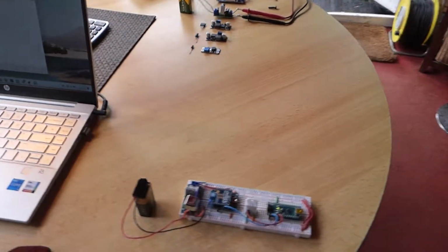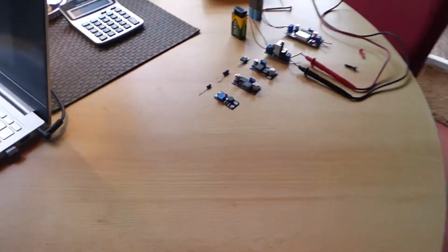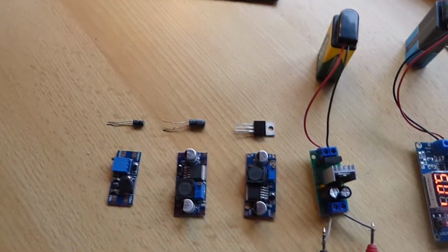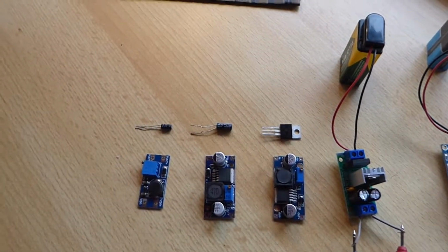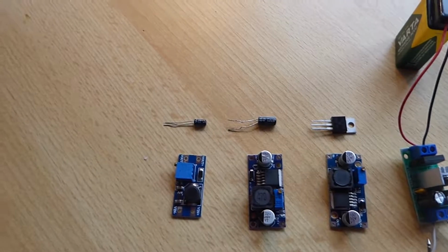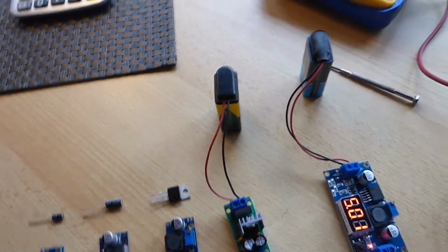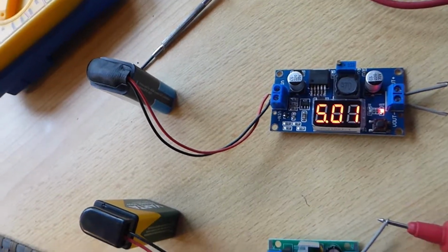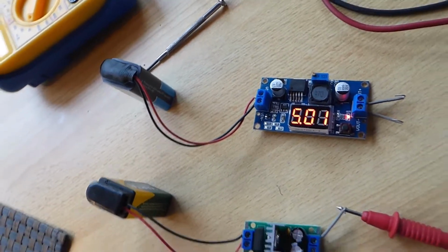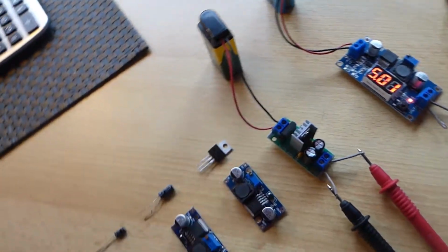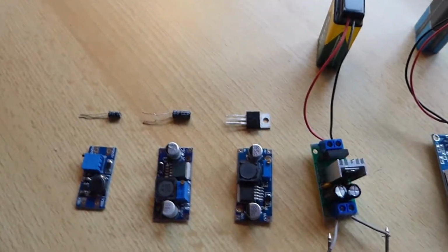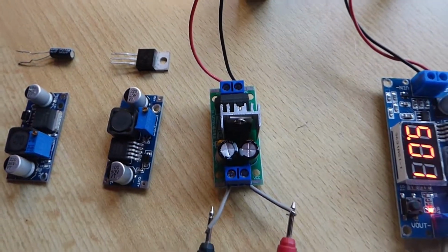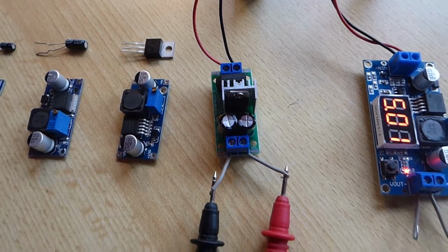Two years ago, when I described the miniaturized system, I pointed out that there were alternatives to using the 7805 5-volt regulator and two electrolytic capacitors, in order to take a 9-volt battery and reduce the power to 5 volts for it to be able to run the miniaturized system safely. Here are some voltage regulators available today.